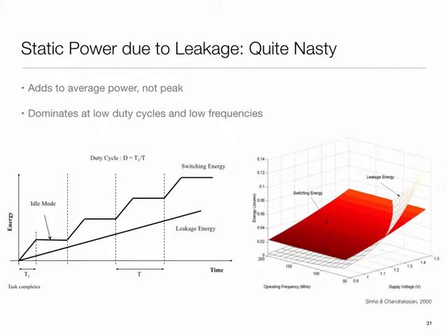Well, if all I'm doing is to idle the system like this, so run fast and idle, what is happening is that leakage energy I'm still paying, but the dynamic energy is actually going to increase because I'm going to be running at a faster clock, and therefore also, to support the faster clock, I'm going to run it at a higher voltage. So when faced with something like this, and you are not allowed to power off the system, then leakage you have to pay anyway, and then you are better off running as slow as possible, using the entire time limit.